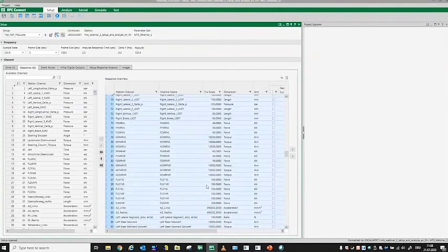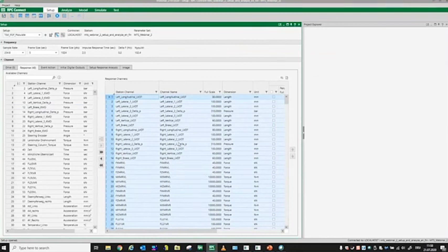So it has 48 channels. And there you go, we replaced the left longitudinal and left lateral. I must admit, what I guess is happening here is that, as I connected the setup using the new RPC Connect file format, it will have two columns available: one is the simulate names and one is the channel names. So RPC always has the information from both, from your EDT and from your setup. What I guess, but I need to verify that, is that it's checking it, and once you use RPC Connect files, it will work fine.